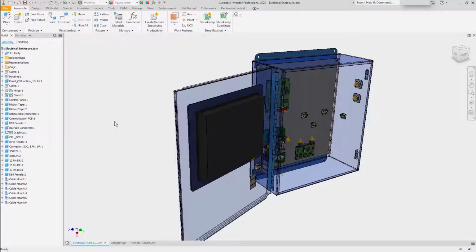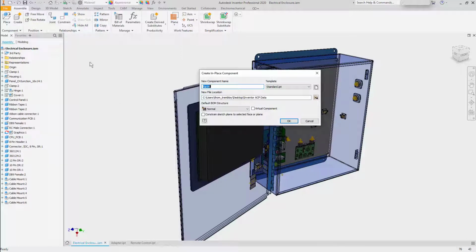There are many ways to create and control 3D sketches in Autodesk Inventor. The first one we'll explore is using work points and sketch geometry to control the position and movement of a 3D spline. We'll start out by creating a new component.